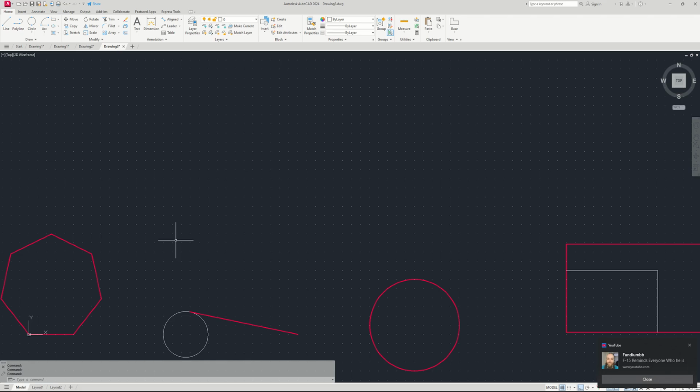Now let's do the other layer 0. I am assuming are construction lines. Now we're going to apply change layer and use it to make a drawing. So for example, I want to now draw a center line. So click the center line layer. Then once you click the line command, the layer takes effect. So I can draw my center line.